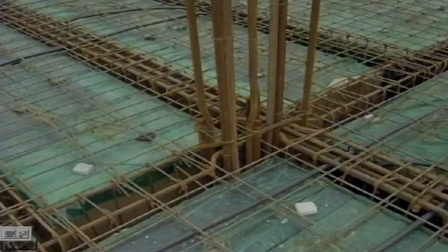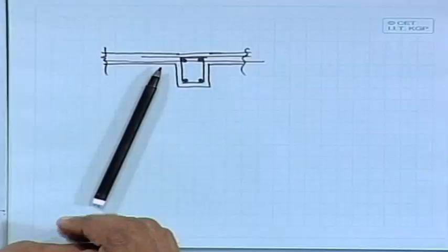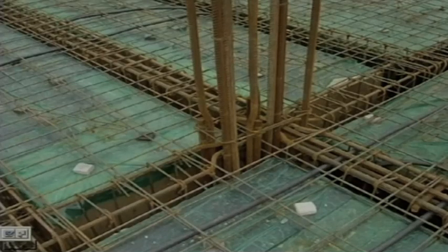Now, when you are talking about this, what is the minimum percentage of steel of the cross sectional area? If B and D are the dimensions, that is the part you always have to take care of. Our code says, for example, for slab it is 0.12% for HYSD or deformed bar, whereas 0.15% for mild steel. So, that is for slab. Similarly, for columns also we have a certain minimum reinforcement that you have to provide, even if you do not have sufficient strength or load applied. Similarly, there is a restriction on the minimum dimension, that means you cannot go less than that value. Generally, we provide 200 millimeter. So, you have to provide all those things.